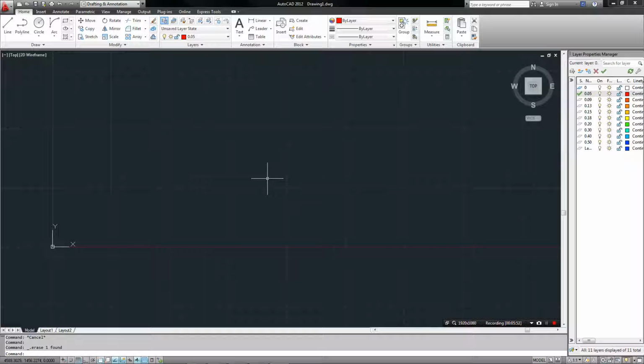The Offset tool. So let's say we have a nice polyline square. We want to offset this. OF, space. Select the amount we want to offset by, or press 50, and then we want to offset that. Oop. Let's try that again. OF, offset. Oh, OFF, that's the problem. Here we go. Offset through by this much. Done. And so now we have an offset line.